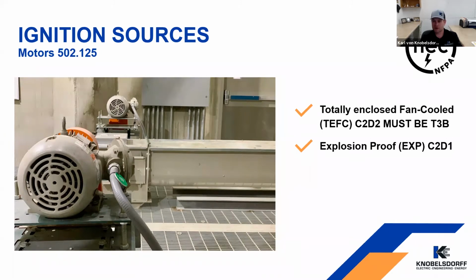Whether it's wheat dust, corn dust, you have to go into Article 500 and 502 and make sure that your T code rating on that motor will work for that location. And this is something that's overlooked a lot in class 2 div 2 locations. You know, you have a motor maybe that was initially installed that worked for that location, but then when it gets replaced because it failed, it doesn't get looked at to make sure that it has the right T code rating on it.